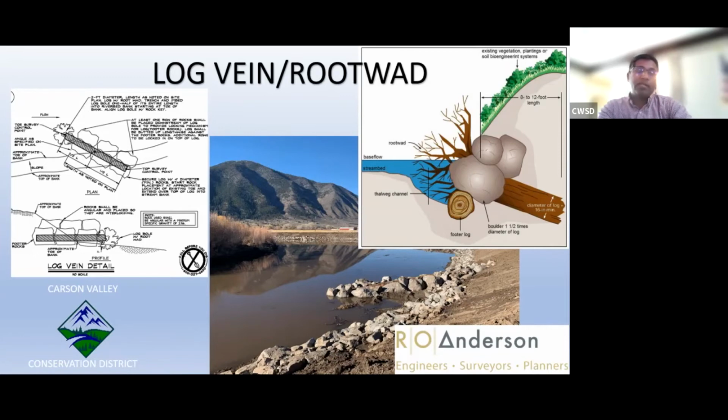So we got this big flood, and the contractor, I believe, obviously we weren't there every single day to watch, right? You were supposed to put big rocks under these logs first, and then cover them, mostly downstream, because we don't want the flow to take away these logs. And I don't believe they had big rocks put in before they installed these logs. As it got a big flood, it just took away some of the sediment, and then these rocks actually sank, and this was exposed. So we were worried that we were going to lose those, and we had to do a change order with them and get those fixed.